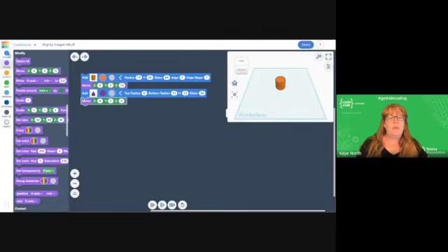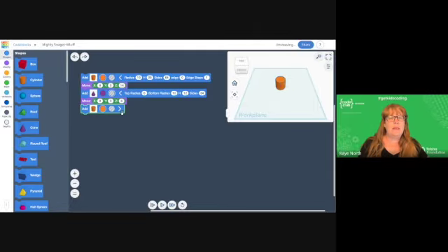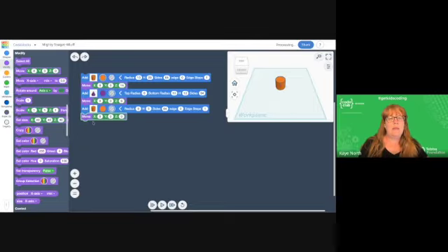Sitting on top of the cone, we are going to put a cylinder. Again, acknowledging that this is a hole, so click on the hole. Our cylinder to match what we've got. We've got a radius of 6. We've got a height of 5, so quite a small cylinder, not very tall. We've got 64 sides to it, and the rest remains the same. Let's now place that into position. Still X and Y are at 0, but Z is at 14.